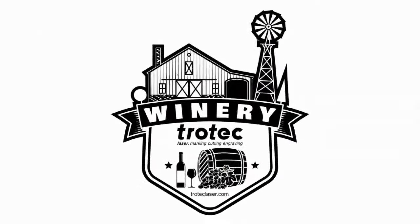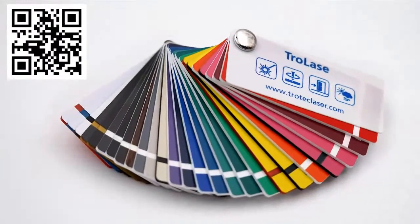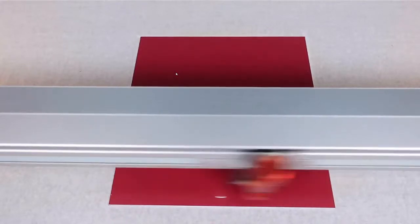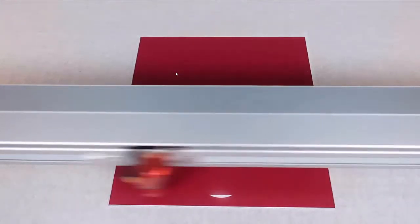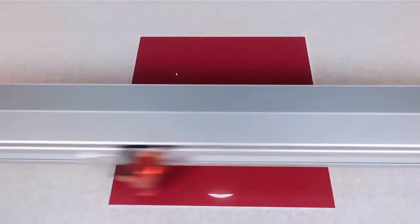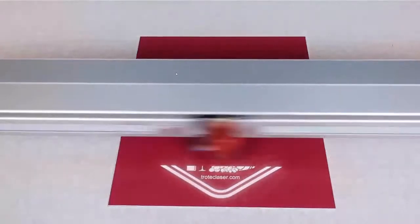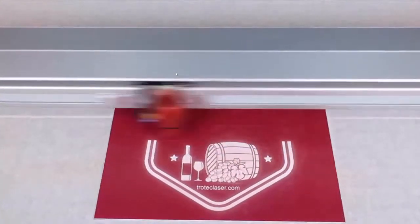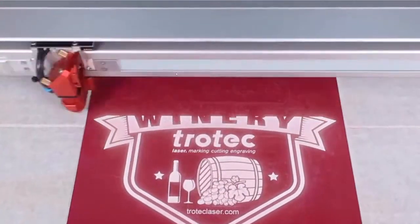Here's a video of the process. What I've done is taken this winery sign real quick, and I've taken the TroGlass plastic. Again, here's a QR code for the plastic that I'm going to use, and I've taken a mahogany kind of wine-colored plastic, and I'm going to engrave it here with my Speedy 400 and I'm running here at 250 DPI, and we're going to do the sign, and this is a kind of a burgundy, kind of a champagne colored color, and then the core is white, and that white background color is what you're exposing when you're engraving this.